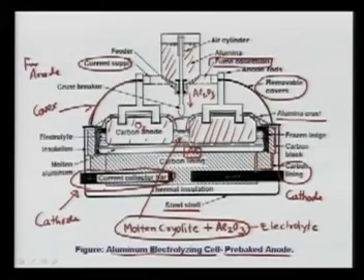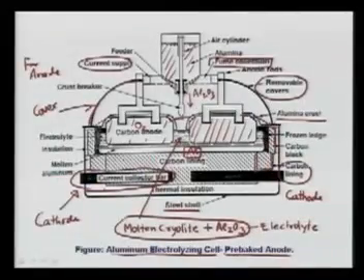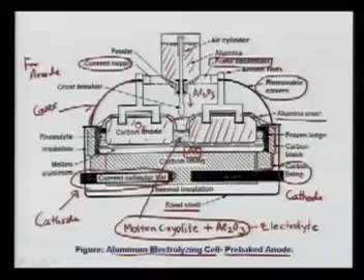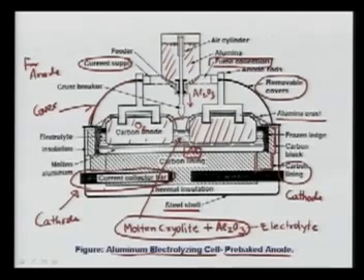Here there is a lot of possibility of emissions, because we have high temperature. We also have some volatilization of the fluoride material, and this fluoride material can tend to go out. The emissions are especially large when the crust is broken, because the whole thing is opened up. We'll talk about the emissions in a moment, but what you have to remember is that this is the electrolysis process that is going on, and the anode is being consumed.